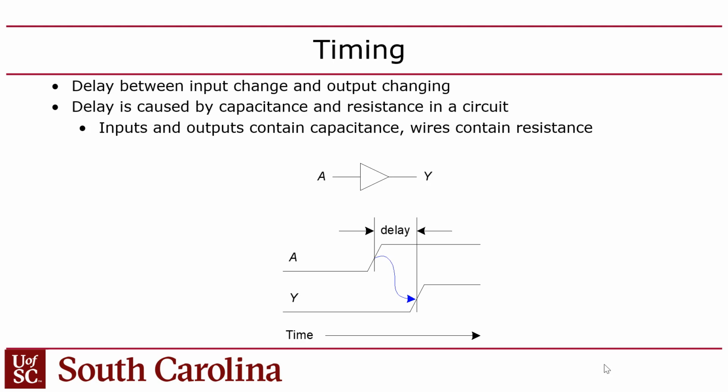When you place and route on the FPGA, you're trying to get the wire lengths to be minimal. So you're trying to put all the gates that drive the signal and all the gates that receive the signal close together, right? Except you have fan-outs where one output goes to multiple inputs, and you can't get them all near each other because you have limited degrees of freedom on a two-dimensional plane, right? So anyway, that's where the delay comes from.